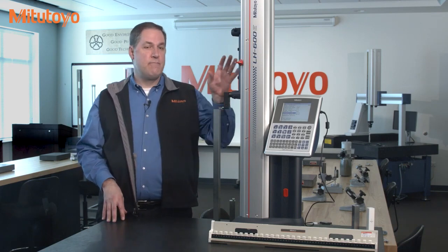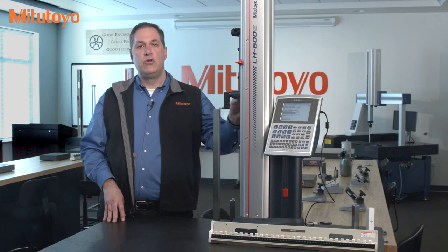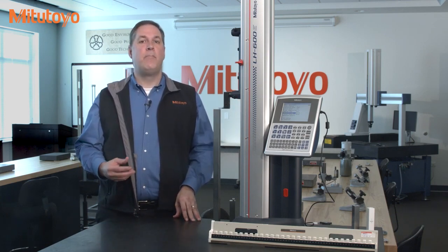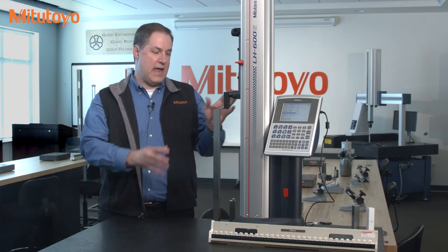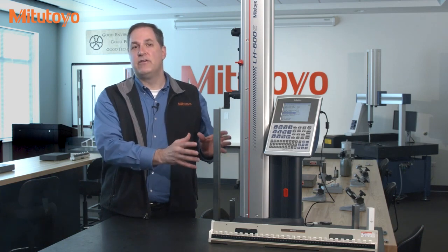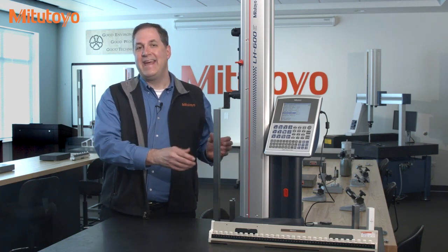Now, in the operation manual for this instrument, you will find the stated CTE to be 8.1 parts per million per degree Celsius. Just as an example, let's do a simple calculation to see what happens if we were to calibrate this linear height gauge using a 500 millimeter, or about 20 inches, steel gauge block in a typical office environment around 22 degrees Celsius.